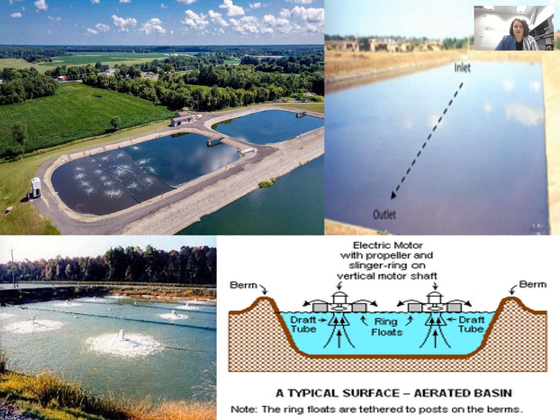So very similar technology, but we're now trying to add aeration. That adds a little bit of mixing to the system, which is sometimes something that we need, but it also adds oxygen to the system as well. So these tend to be a little bit more aerobic in nature and can be used as a secondary treatment process.